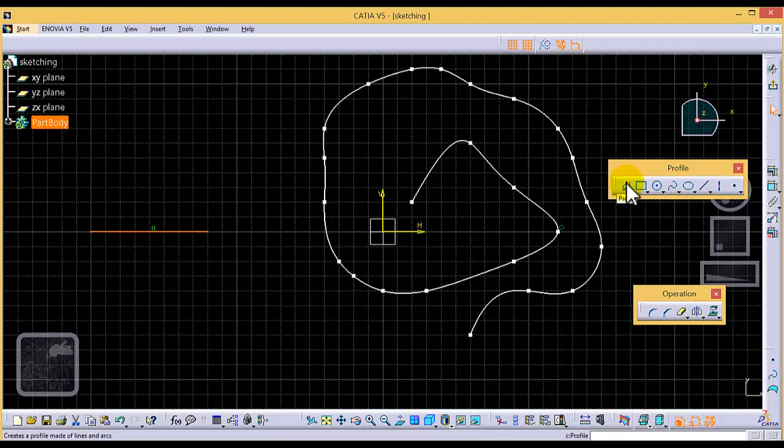If you are in the profile command, you can continuously sketch different lines, horizontal, vertical, and at some angle, like that. Again, we need to select the line command if we want to draw another line. Then there is an axis. You can also draw an axis, and there are also points, so you can simply put a point.